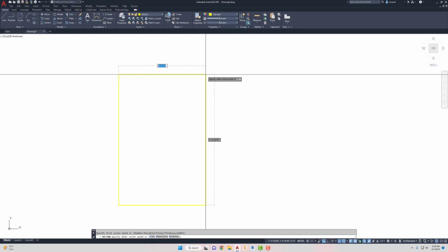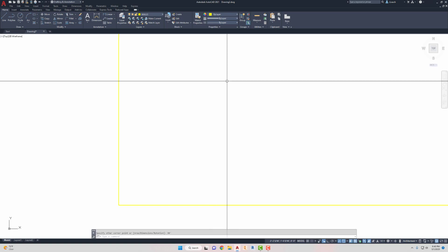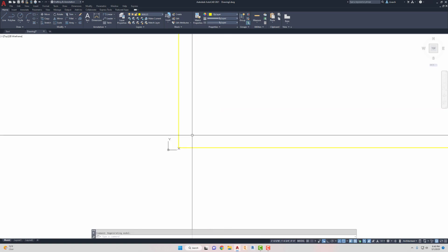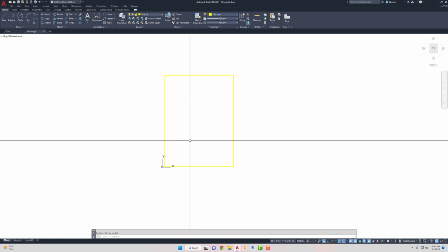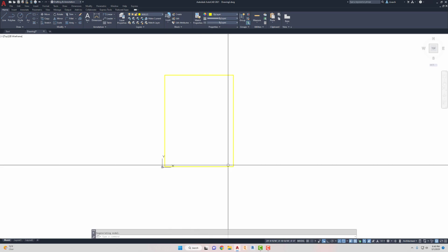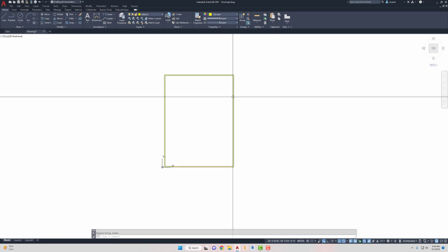Okay, so anyway, you notice the highlighted part right now says 10 and 9/16. I'm going to change this to 30 feet. I type in the foot symbol, hit the tab key, and then type in 40 feet. Hit the tab key again, press enter. Let me zoom out a little bit. So that created a rectangle that's 30 feet wide by 40 feet tall.